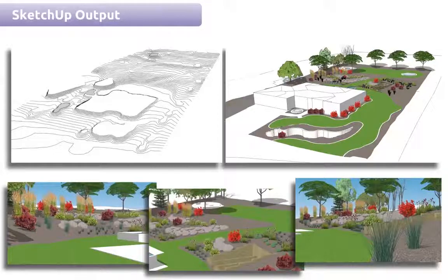Ultimately, it's going to just come down to processing time. Unless you're working on an enormous site, it's going to process it, and it's just going to take longer. Say a typical site of maybe 5 acres that has 100 images that you're going to be processing. If you process that at full or a little below full resolution, it's going to generate the point cloud, the model, and the contours in about an hour and a half to 2 hours.